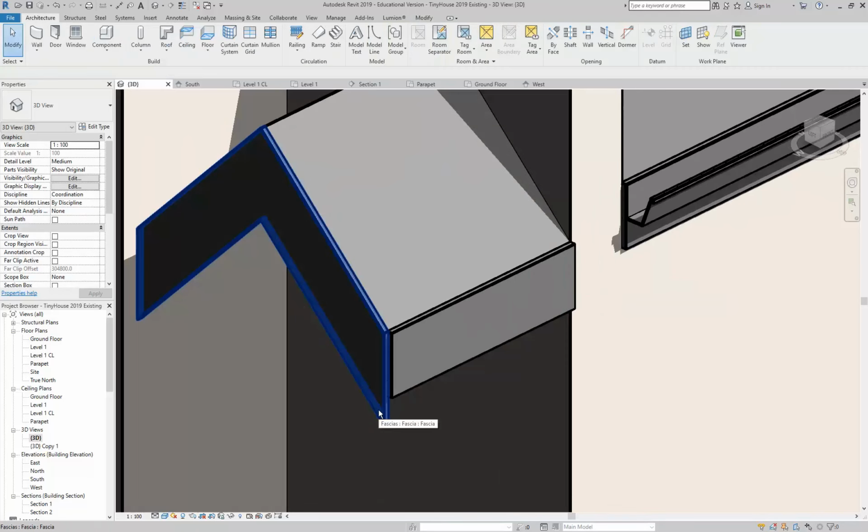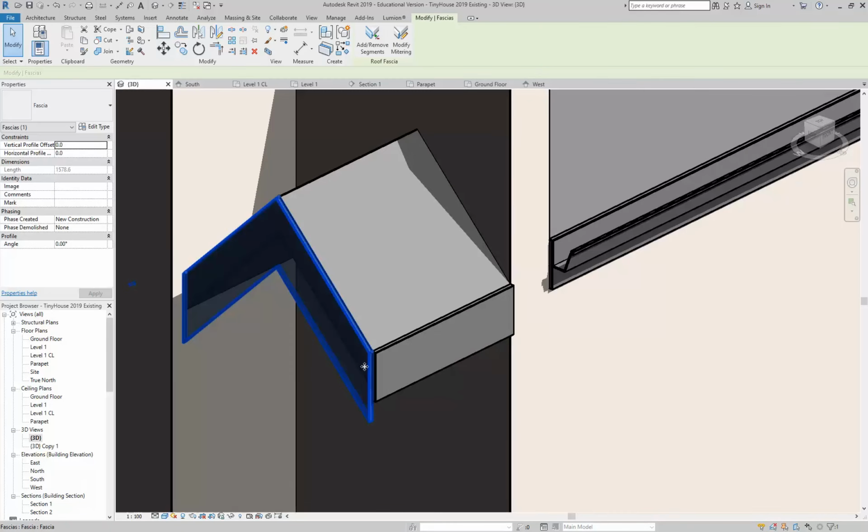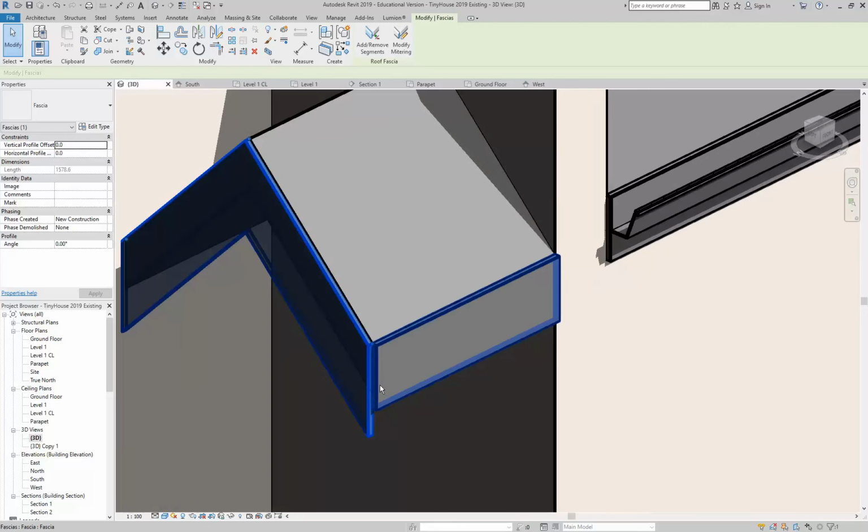Why would we not want them connected? Oh, well, typically, so this one's called a barge board, and it wouldn't be connected to the one on the side, and also you want the option to be able to stretch that out so it can project and hide the gutter. So that's typically the way these are built.